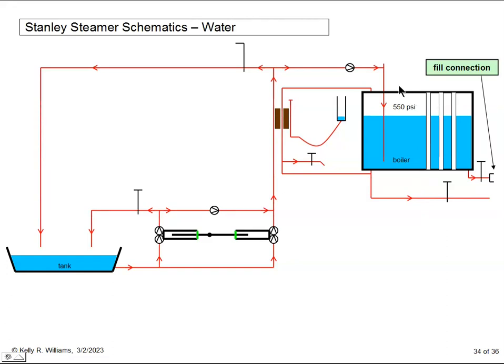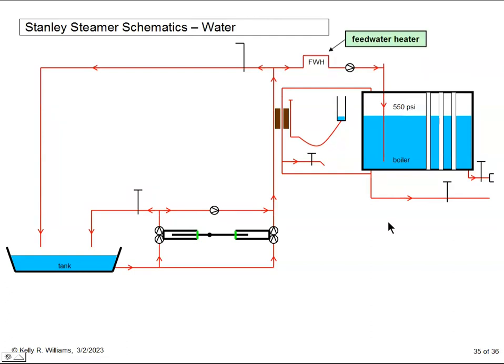The energy that does get into the steam is not all used by the engine, and the engine exhaust is still pretty hot. In an effort to recover some of this energy, the feed water line at this point is diverted to run through the engine exhaust pipe and come back again. The water in the line picks up some heat from the exhaust, so the burner doesn't have to use quite as much fuel to heat it up to operating temperature. The FWH here refers to this feed water heater.